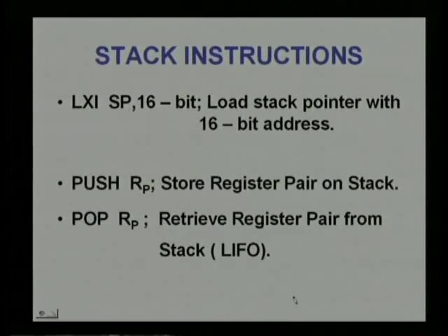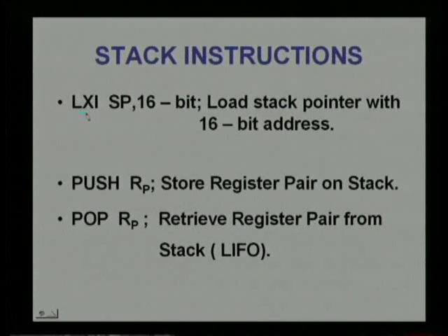Now let us see some of the stack related instructions. Whenever we use stack, first we have to initialize it by writing the top of the stack address into stack pointer. That is called stack pointer initialization. It can be done by simply loading 16-bit operand, in this case it is address, into stack pointer register. You know, stack pointer is a 16-bit register. So, this is the first instruction, LXI SP comma 16-bit. It loads stack pointer with 16-bit address.